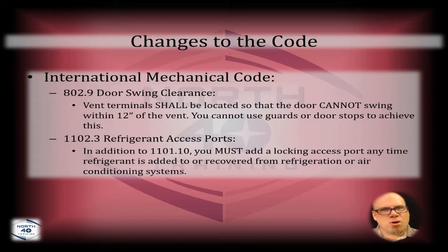Moving those vents over is clearly the best case scenario because then you're not going to damage them with the door, even if code didn't tell you to do so. It would make a lot of common sense to not put that someplace where a door could hit it. And there's all kinds of different places in all the codes that say that you're not supposed to run stuff through or obstruct an openable door or window, so it's just common sense. And could be bad mojo to do so anyway.